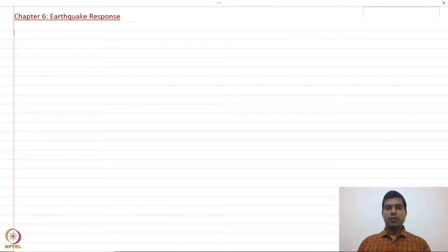Welcome back, everyone. We have seen so far in this course how to obtain the response of a system subject to either well-defined analytical forces like harmonic forces, and we also discussed how to get the solution if there is an arbitrary excitation. And in the previous lecture, we saw that if the loading cannot be expressed as a closed form representation like p(t) equal to some function, then how to employ numerical methods to obtain the solution.